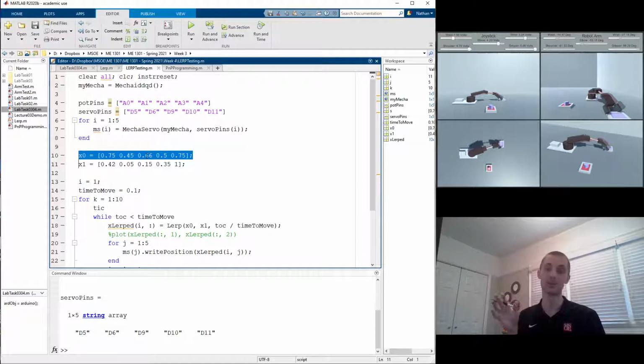Literally going through the task of picking and placing is one thing, but when you're trying to slowly pick up a block and then move back and then rapidly go forward and let go of the block, you have to move at a different speed every single time. And the same is true for the pick and place. If we don't want that block to fly out of the gripper, we should set a specific time for it to move from one point to the next. So I need multiple locations, like snapshots of movement throughout, and a speed at which I want to perform that movement.